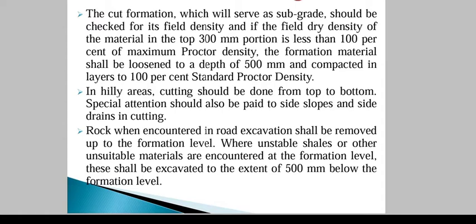So this filling we'll see. Next is the cut formation, which will serve as subgrade. As we are cutting the surface of the natural ground, the lowermost layer can act as a subgrade if it is of good quality soil, or if it is hard rock. Most of the time we try to avoid cutting rocks to lesser depth.